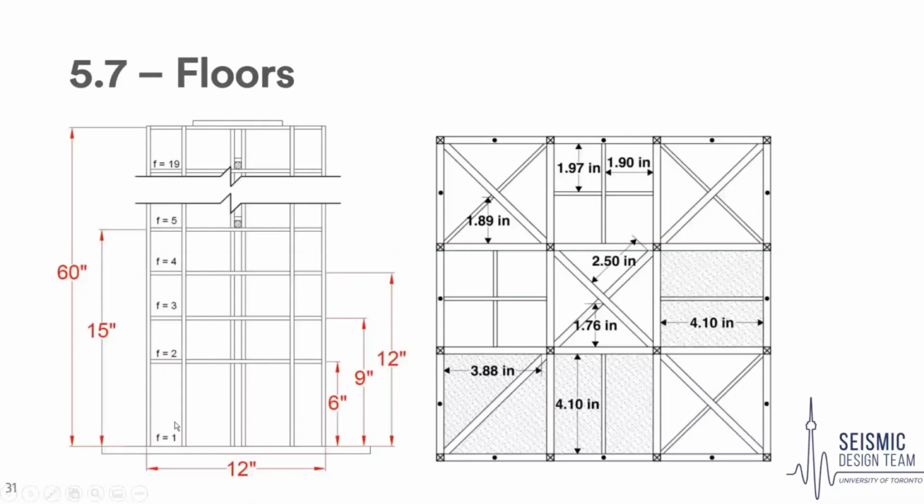And then on the right, this is a better explanation of that rentable floor area. So they took a bunch of distances perpendicular to various members. So notice they're not taking the distance from here to here because that's not perpendicular to anything. So they took, for example, this distance perpendicular to this member, farthest distances to here, that's greater than 2.5 inches, so this doesn't count as floor area.